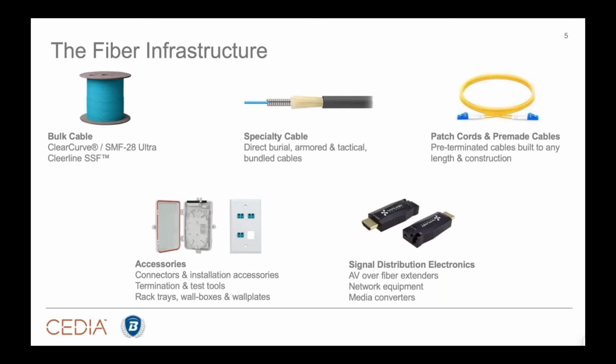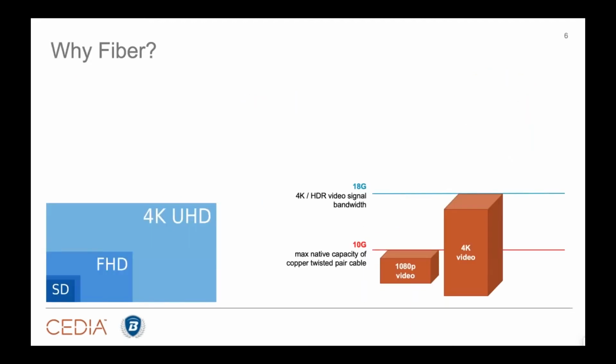Here's the thing. We never really needed it for the bandwidth. We never really needed it for a lot of the different properties that we're seeing affect the installation today, the AV installation. We'll talk through this here in a minute. But what's really important for AV is there really wasn't a lot to plug into your fiber. There weren't little black boxes that actually let you use it effectively for things like HDMI or network switchers with fiber ports. It wasn't a thing that was really prevalent in AV installations. That's changed. We have black boxes now. We have to think about what type of devices I'm going to be plugging in, because here's the deal. The signal bandwidth that we're working with today, the resolution, the size of these video signals, you have to use fiber. We're going to talk through this, right? And I'm sure that you have done an AV installation before. You are familiar with the evolution of video in our industry, right?